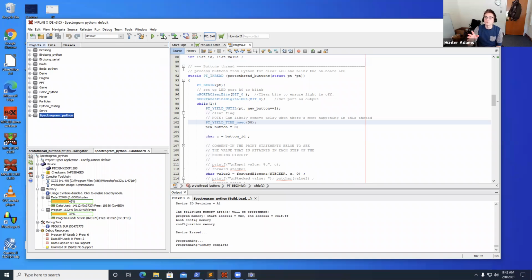So if you were playing a pure tone at 400 hertz, then your FFT would be a big spike at 400 hertz. If it's composed of a whole bunch of different frequencies, then you would see a whole bunch of different frequencies in your FFT. The spectrogram is a way of looking at the time history of the frequency content of sound.